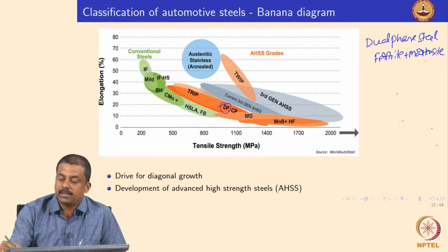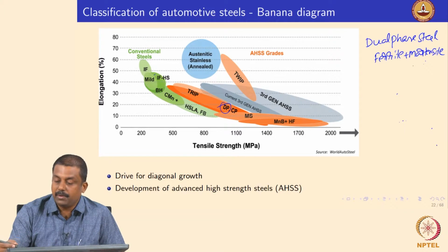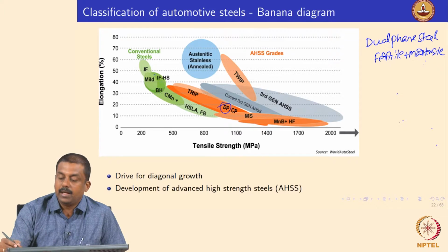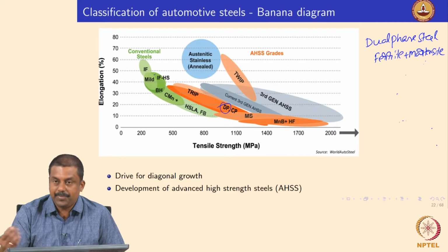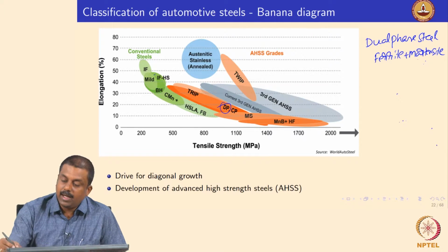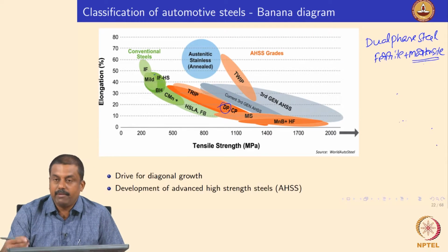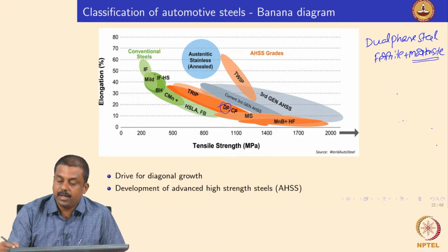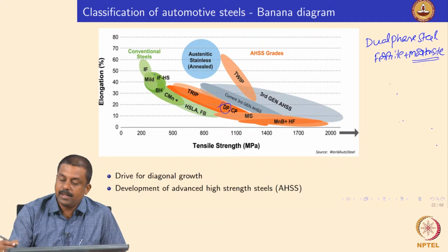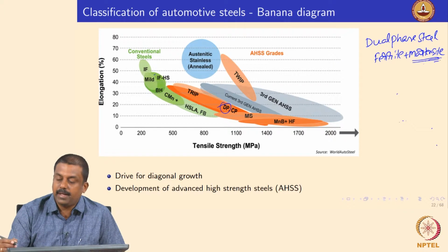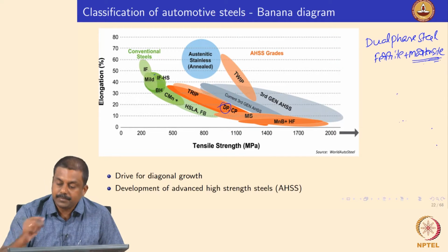As already explained, the martensite actually forms from the austenite when you rapidly cool to room temperature, in a diffusionless or displacive manner. And the martensite also provides a very high strength compared to the ferrite. During this process of martensite formation, there is also a considerable volume increase, expanding the crystal structure when the FCC transforms to body centered tetragonal.